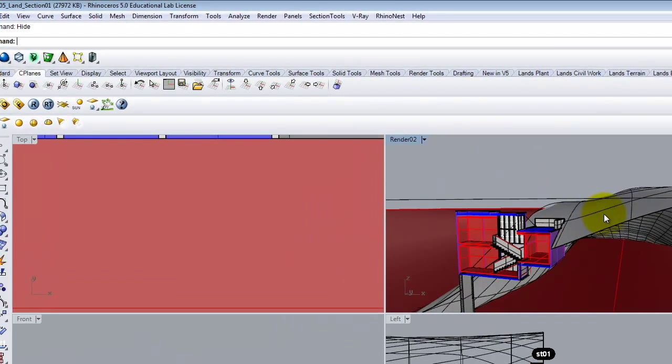The problem here is that if I were to render it, this works kind of like SketchUp does, where this whole side of the building is open, and all the light and all the sun and everything wouldn't follow through, and I wouldn't get little patches of sun where it's casting through windows, etc. It would just be wide open. And we're using way too sophisticated of a program to just default into that view. So we're going to take that back, and I'm going to go to Show.